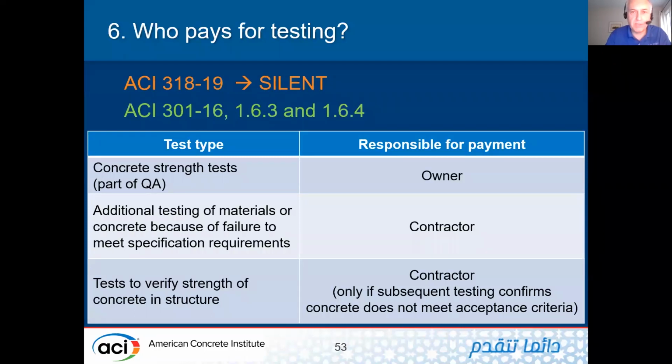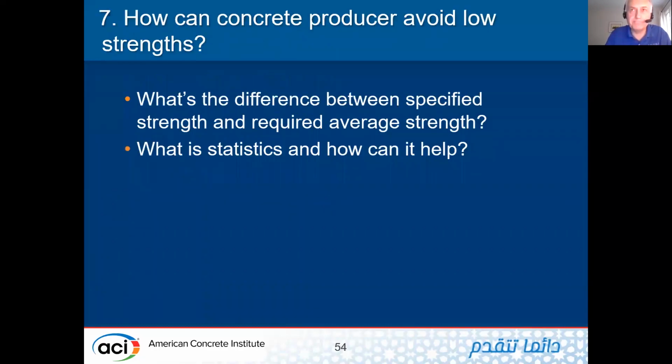So again, this is about payment, but again, every project is different. And from my experience, I say that this is not really binding because the specs for every single job are a little bit different. And oftentimes when you have a reference to other specifications like ACI 301 or different specifications, hot concrete, cold concrete, curing and so on, typically there is a language saying that in case of conflict, the provisions of such and such specifications govern. But again, if you need some of that language, this is where you find it.